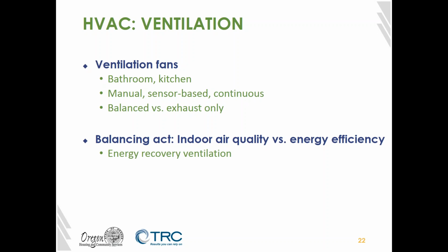A way to mitigate that energy penalty is by looking into ERVs, energy recovery ventilation, or HRVs, which is heat recovery ventilation. And those will run the two streams of air, the air coming into the building and the air going out of the building, past each other, and they transfer heat between each other, so you have partially conditioned air, so that you don't have to condition the air that's coming in quite as much.